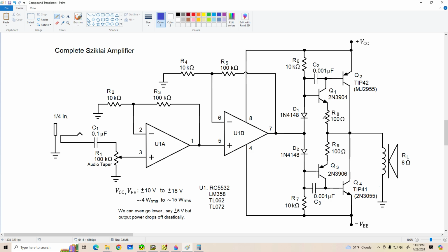The function of these resistors, well, it's twofold. First of all, because I don't have matched diodes with these transistors, there's a chance that I could get more current flow than I'd like. So R8 and R9 help to reduce the chance of overbiasing the output transistors.